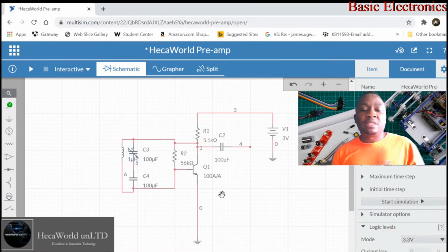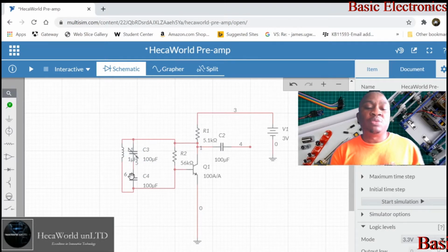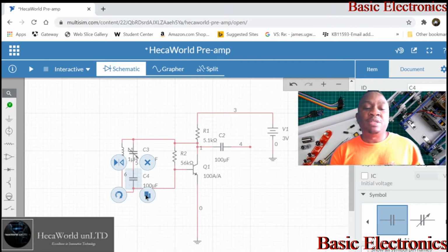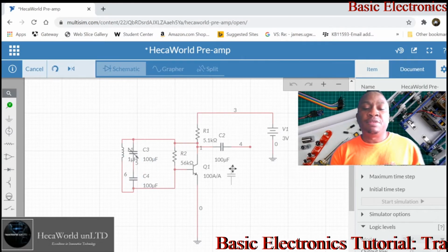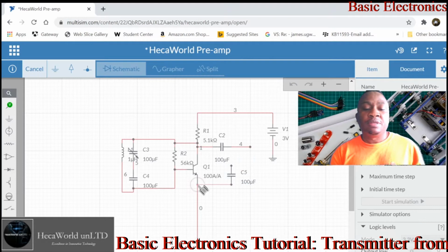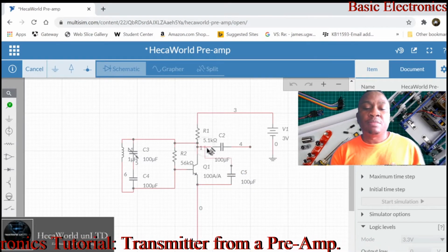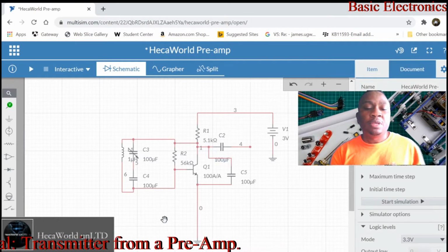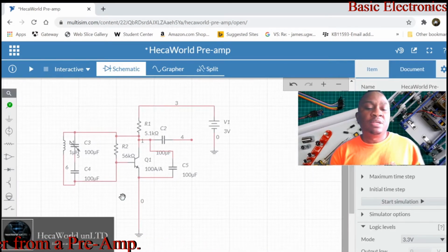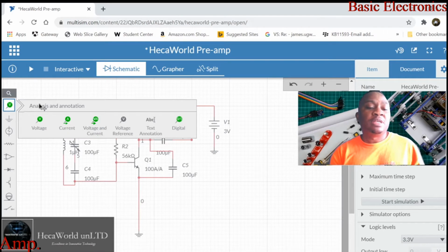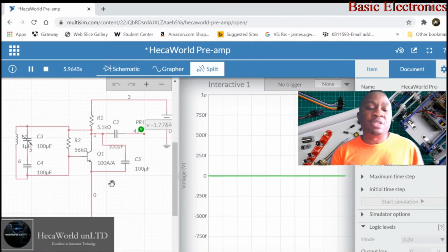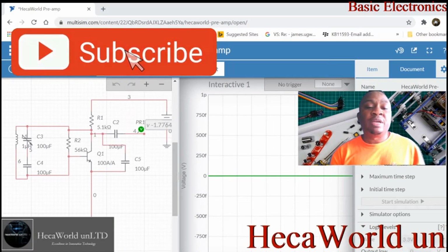So basically this is the frequency determining network, and to put in our feedback network, we can just have a capacitor connected across this way. With this circuit the way it is, we have just built ourselves an oscillator. So I'm going to put up the circuit diagram of the oscillator, and we're going to go and breadboard what we have just created right now.